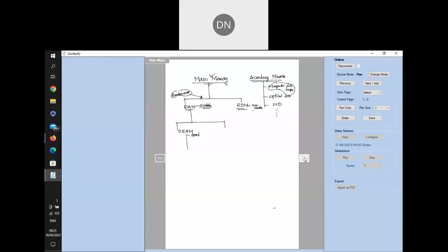So in main memory, if somebody asks what is the memory of highest speed, SRAM is the highest speed, and it takes more space compared to the other types of RAM. More space it takes, and the cost is more. Why? Because, as we will come to know in the construction, it requires more number of transistors. So to reduce the cost and to have a large number of memory cells in a given space, to increase the density, DRAMs are used. DRAMs are popular for high density of the memory. That means more memory cells can be put in the given area, and the cost is less. DRAMs are cheaper, but they have their own constraints. We will study them in detail.